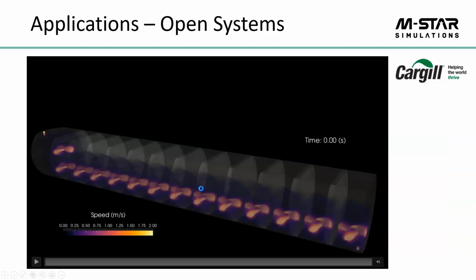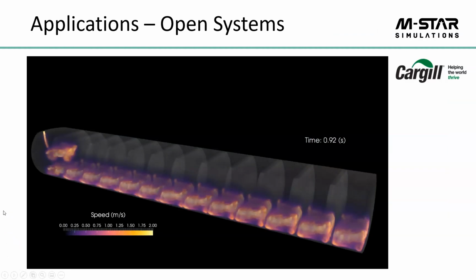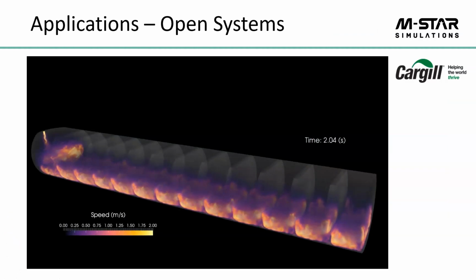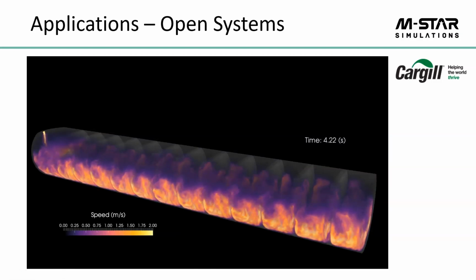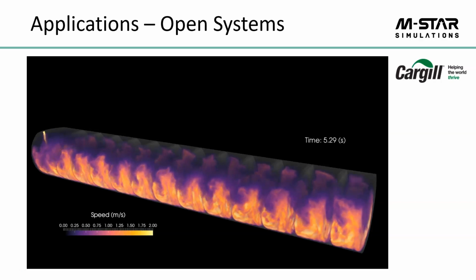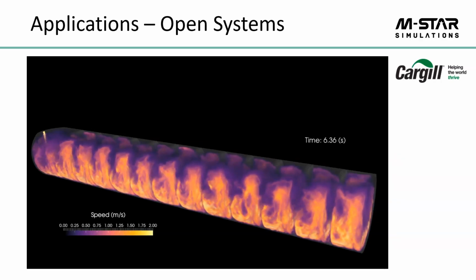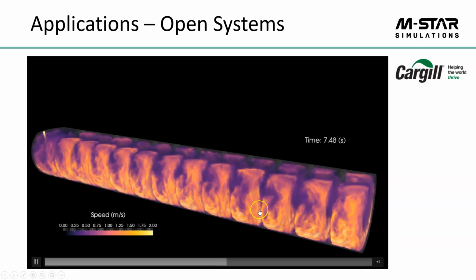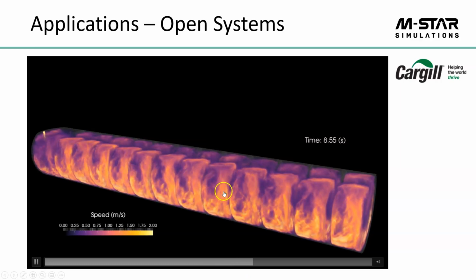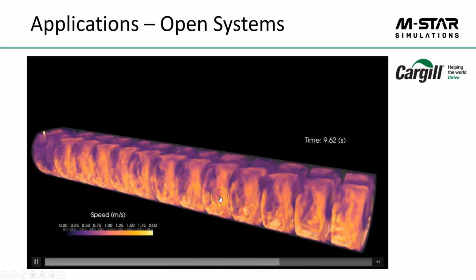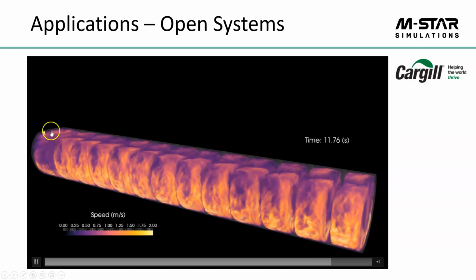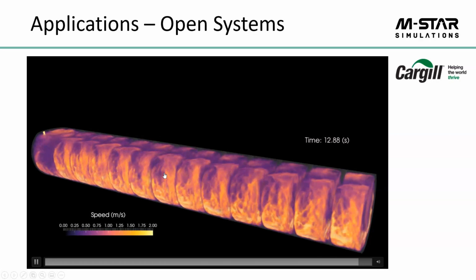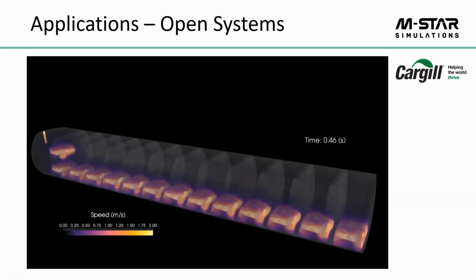Carrying on, this is not just for a single vessel. Here's another great example. This is a 13-chamber CSTR with a mean residence time on the order of an hour or so. And look at the heterogeneities in the flow field. We have individual agitators inside each cell, leading to high mixing inside each cell. Superimposed on that fast mixing is very slow bulk flow through the system.